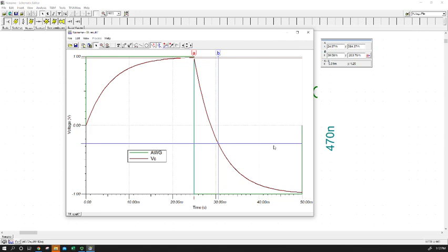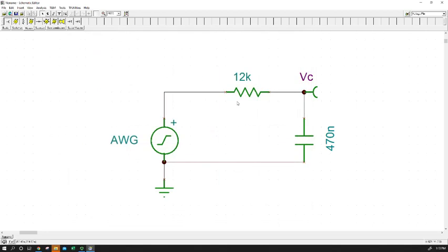So when we look at our predicted values and what we expect to get in our real circuit, we need to bear in mind that the simulator is going to zoom in on design flaws that don't take into account real components. It allows us to not have that distraction and get a good simple idea of what's going on. It allows us to eliminate variables that we don't want to consider, but it can't see what it doesn't look for. Because we're not accounting for the fact that we could have different values of components, there is a precision range. We aren't including noise. We aren't including the additional resistance or capacitance of leads. So the RC that we measure could include more than just the R and the C in our circuit. What we measure may be somewhat different from this.